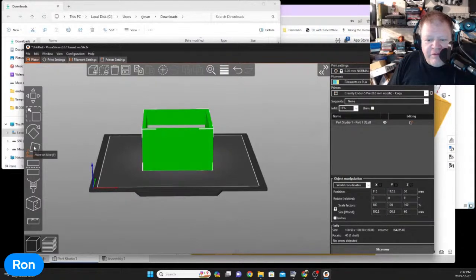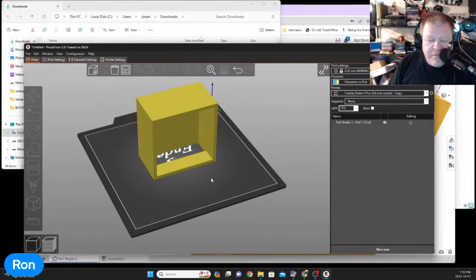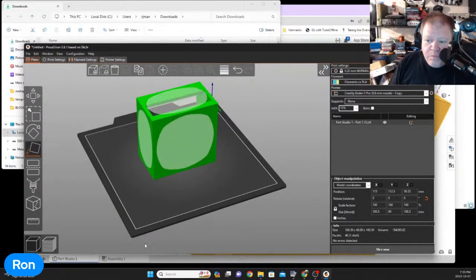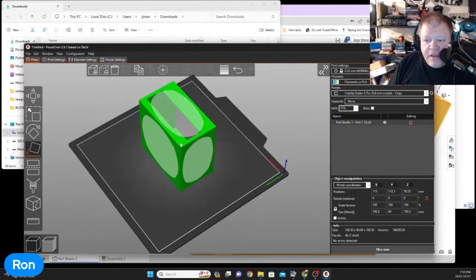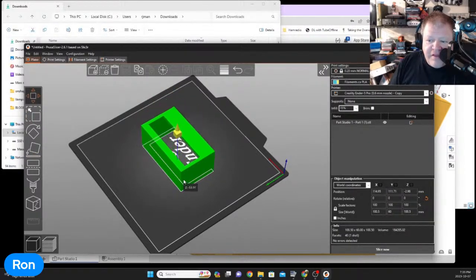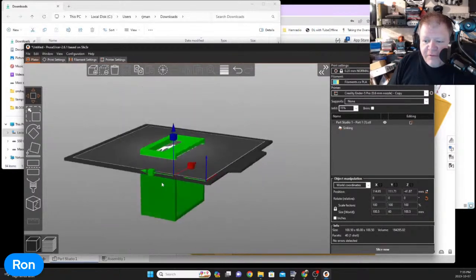So what I'm going to do is use some tools here. Place on face. So I'm going to hit the front face here. Boom. Like that. That's it. Actually, you know what? I did it the wrong way. Boom. So then I can go on here, hit the button, and sink the file down, all the way down to as far as I want to.